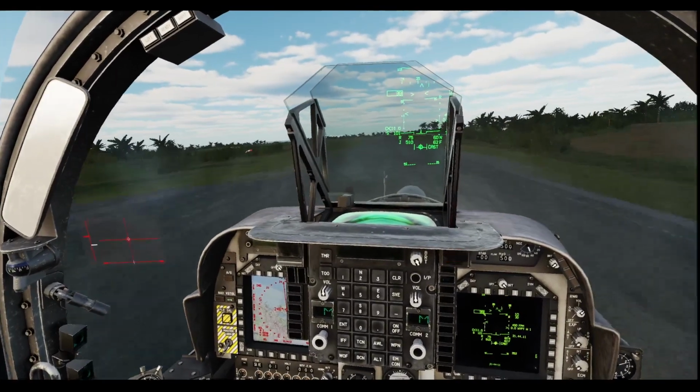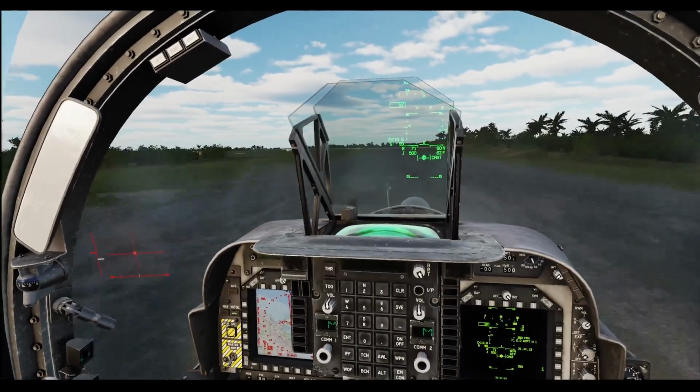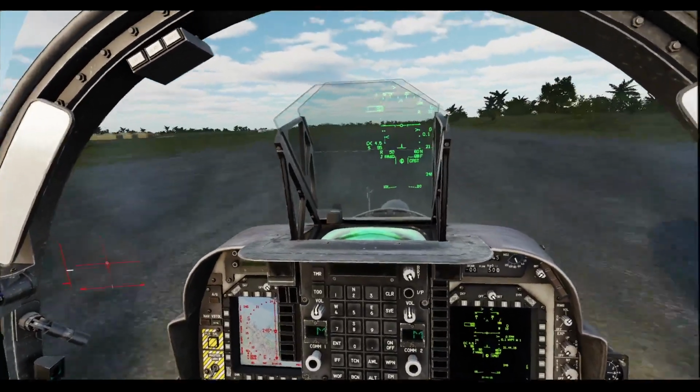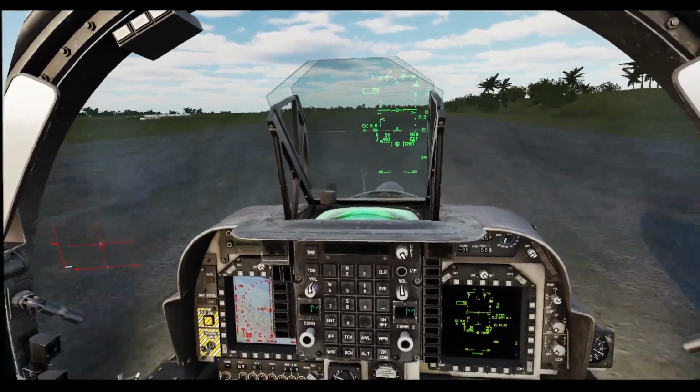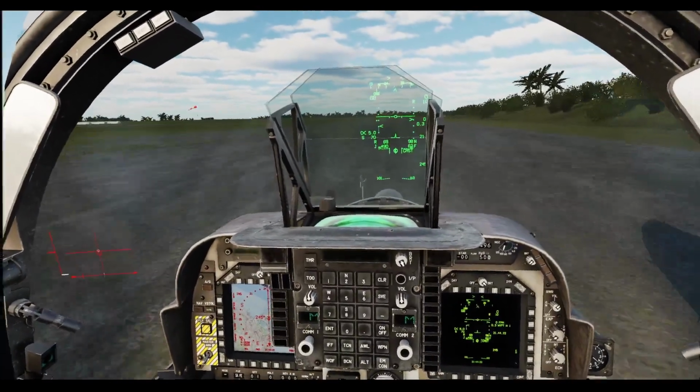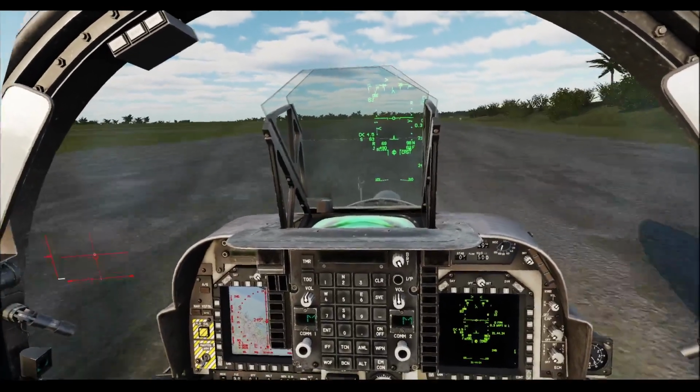Which is hot on the horizon, adjust the power, maintain the airway, no more than 500 feet per minute, kick off the drift, opposite aileron, close the throttle, bring the nozzle back positive, nozzle braking, use the rudder to keep it centralized, no more than 70% RPM during the braking, wait until we're less than 50 knots,